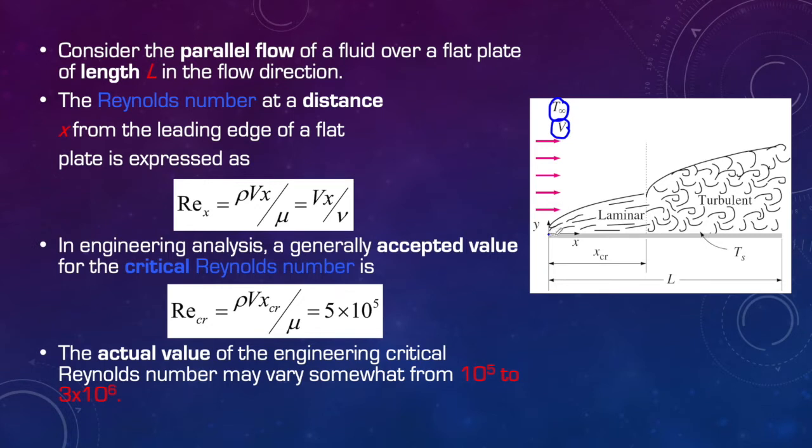When fluid layers stick to the surface, it will affect the other adjacent layers. The affected layers will increase as the x coordinate increases. If we combine all those affected layers, it will create a hypothetical path here. This is what we call the boundary layer.